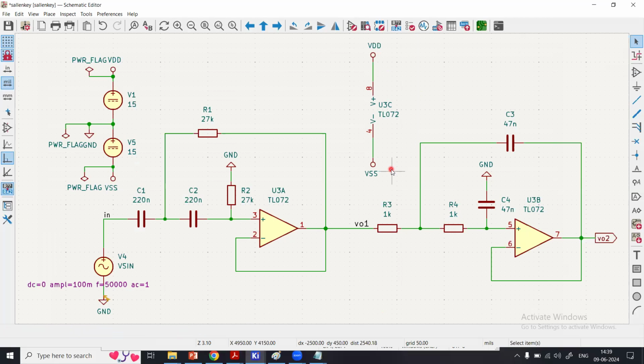You can just type the number in Google and you can get access to how much is the offset voltage, how much is the power consumption, how much is the bias current, CMRR, PSRR, maximum supply voltages that you can use, and so on and so forth. So all this information, if you are critically designing or optimizing your electronic design for those specifications, to meet those specifications, you need to refer to the data sheet.